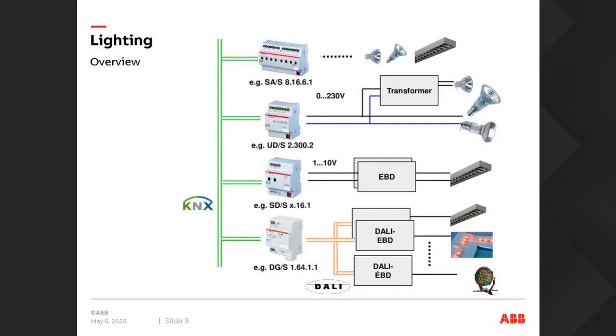So we have our ABB DGS 1.64.1.1. That's one of our big selling devices. We have a DALI line coming out of that, controls up to 64 devices, so it's quite commonly used in lots of installations.